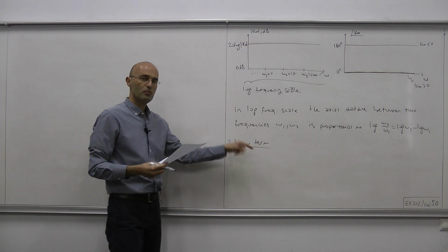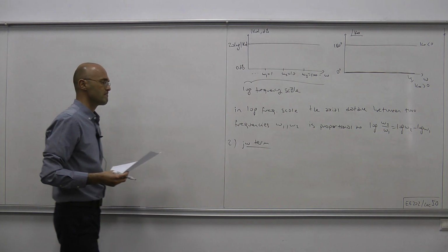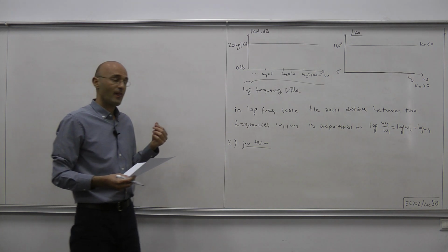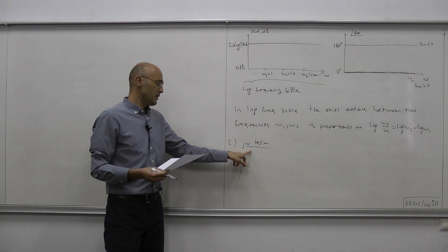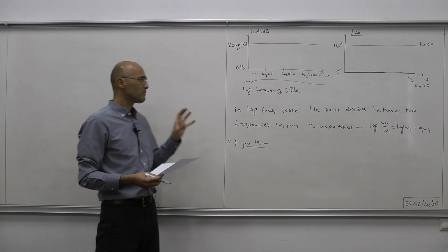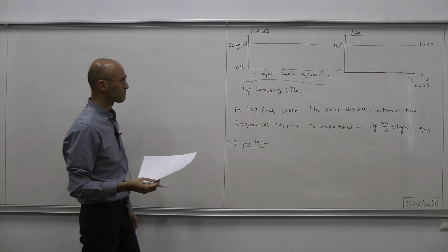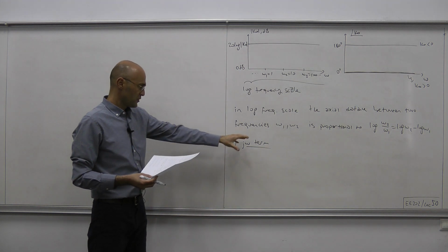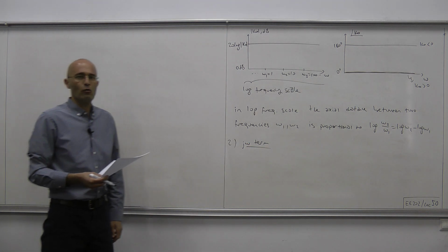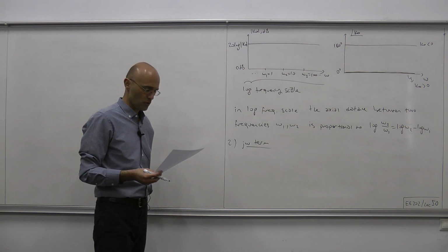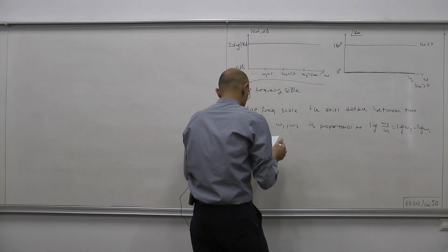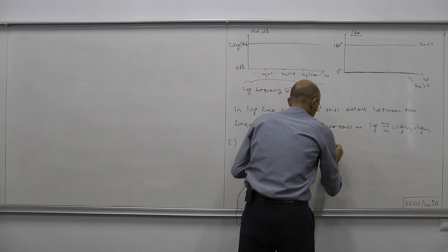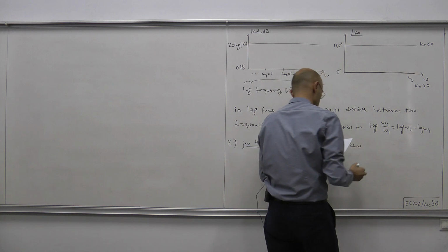So we had a j omega term in our example due to the 0 at the origin. We may have had also a pole at the origin, then we would be dealing with a 1 over j omega term. But since we are dealing with the gain in terms of decibels, the treatment for j omega and 1 over j omega is almost identical. It's just a matter of plus or minus. So this term is due to a single pole or 0 at the origin.